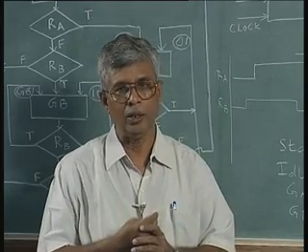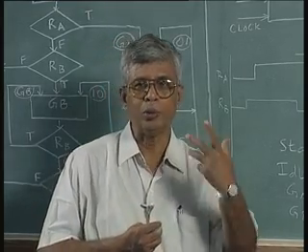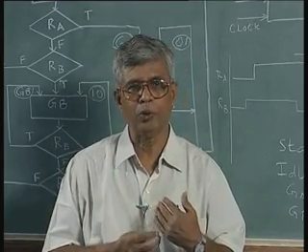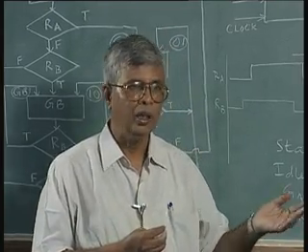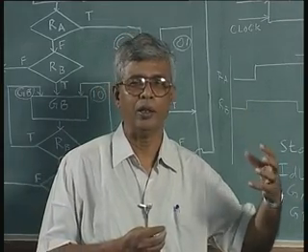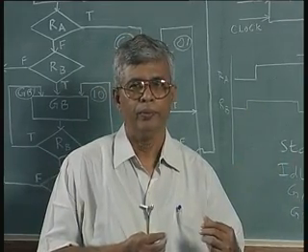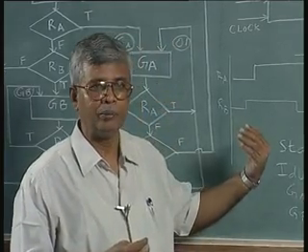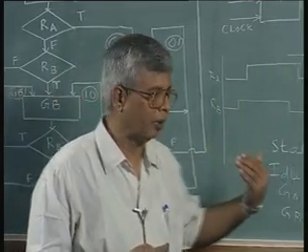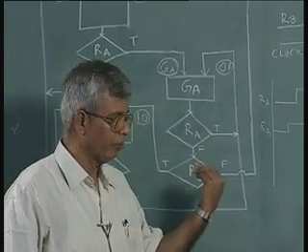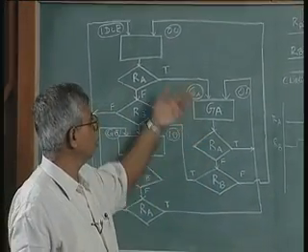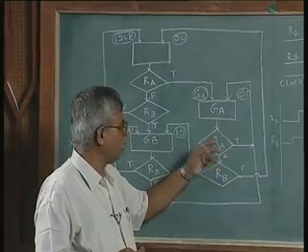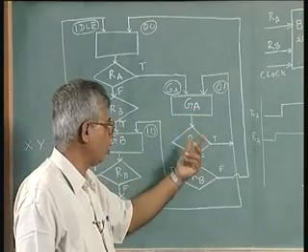Then go to the controller, find out what are the external inputs and outputs required, and then use these inputs and outputs from the functional units to identify a clear block diagram of the ASM controller. Once you have that, you go to the ASM chart, and the ASM chart is the most critical thing because it has to be done properly, time wise. So, you have to time it properly. For example, this is an important step, I would say: GA has to be kept on as long as RA is high.